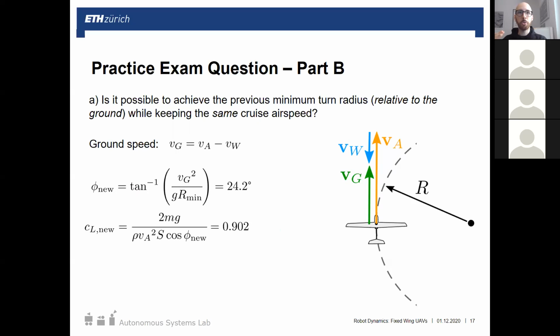Maybe they know that that's the optimal angle of attack and they want their fuselage, for example on a scanning UAV or something, in a specific orientation that's quite flat, but they want a more optimal angle of attack for range or for endurance for their wing. In the general sense, they might put that incidence there.